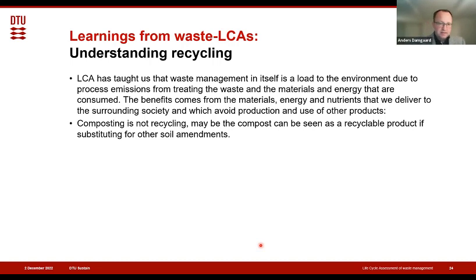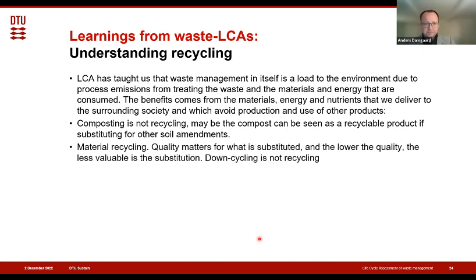A lot of the early LCAs were very focused on material recycled, avoided good. But this is where we started saying composting is not really recycling. It might be seen as recycling, but it's really only in the case where the compost can act as a recyclable product and substitute for other soil amendments that we can say there is a credit for doing this. And this is because often we have a lot of low quality composting facilities where the materials will not substitute anything. They might end up as a soil cover on a landfill.